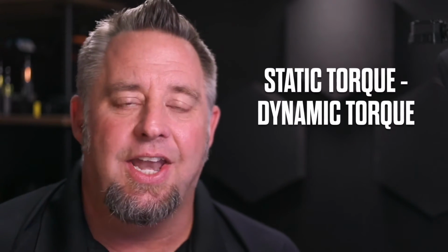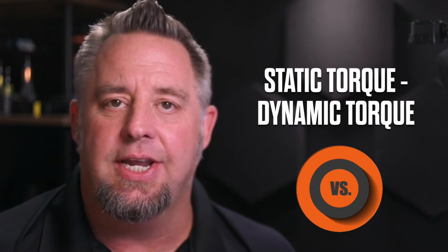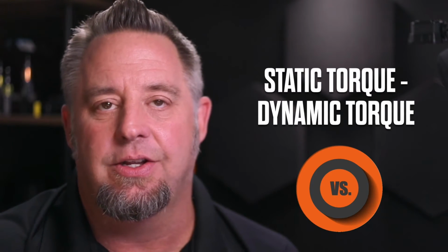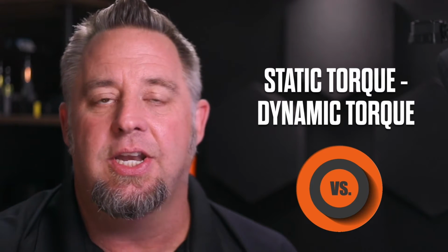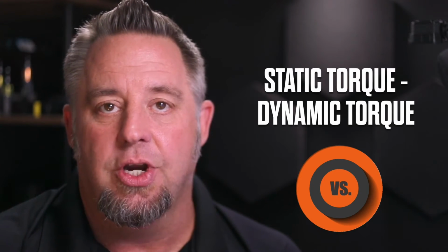As we look at the different areas of torque and when we're doing our measurement, oftentimes you'll hear the terms static torque or dynamic torque. Static torque is a measurement on a fastener that has already been assembled. Dynamic torque is where we're measuring as we are doing the fastening process. This also may come up when you're dealing with torque sensors. A static type of sensor does not have any movement in it; it will be a reaction style transducer. A dynamic sensor will be a rotary type of sensor, where you have the ability to actually measure while things are turning. That's the difference between static torque and dynamic torque.